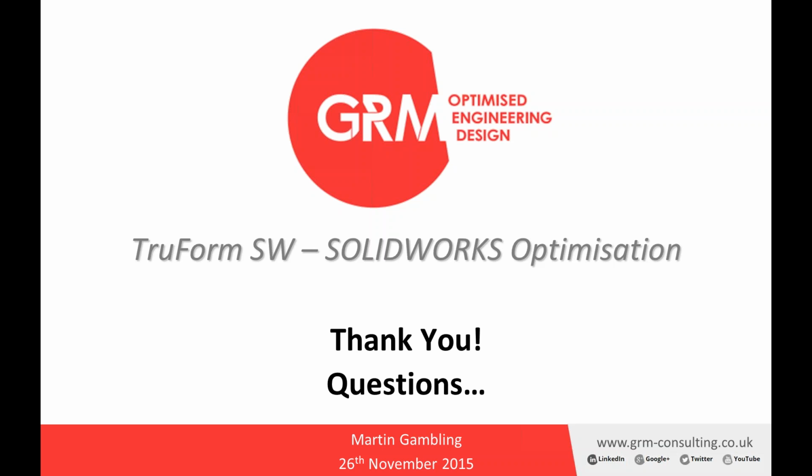Okay, got another question there. How long does it take to run the optimization? Depending on the refinement level that you're working on, the coarsest optimization level will solve in about 1 minute. Standard is about 5 minutes, and the highest refinement, which is what was used for the motorcycle bracket, solves in around 45 minutes to 1 hour to present your answer.